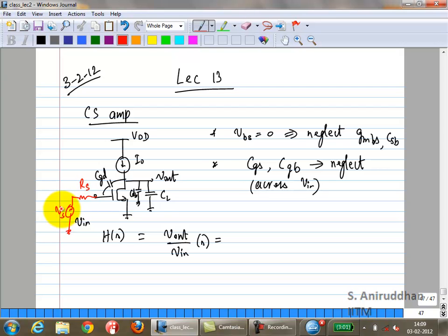So as far as the signal goes, you can completely neglect the transistor. There is no signal going through the transistor. What about the other path? Are you going to short the capacitors? The capacitor divider, right? So in other words, you can short the capacitance when there are no other capacitive paths. If you have other capacitive paths to that point, you can't arbitrarily short it. Okay? Just remember that. So in this case, you just find out the voltage, very easy.